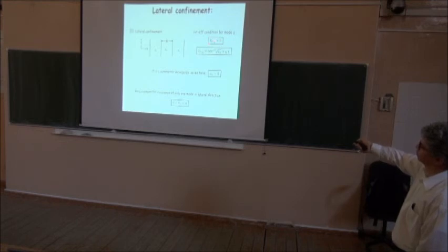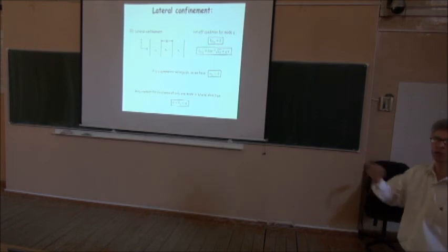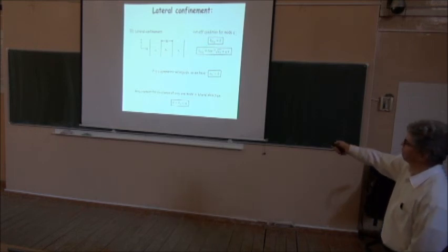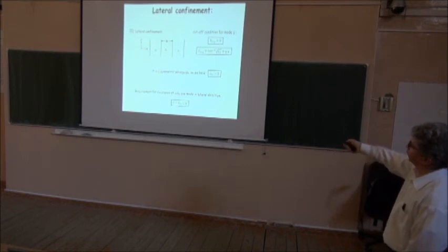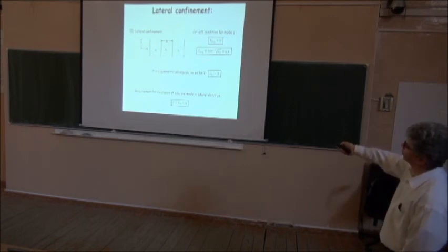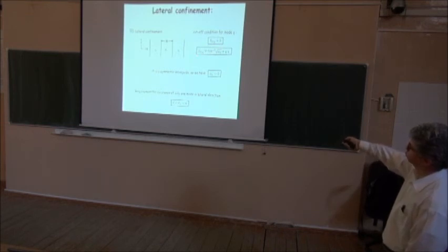In this case, the B2 needs to go to 0. That's the cutoff for a particular mode along that dimension. In this case, this is a symmetric waveguide, so the asymmetry factor is 0, and the appearance of a mode is regulated, so this term here is going to go to 0. So the appearance of a mode is just Q times pi.